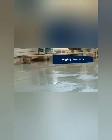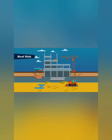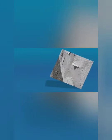This is generally observed in a highly wet mix, badly proportioned and insufficiently mixed concrete. It is also observed in thin members like roof slabs or road slabs and in sunny weather conditions. Sometimes, along with water, a certain quantity of cement also comes to the surface. During finishing with the trowel and floats, the aggregate goes down and the cement paste comes up to the top surface. This results in the formation of laitance.